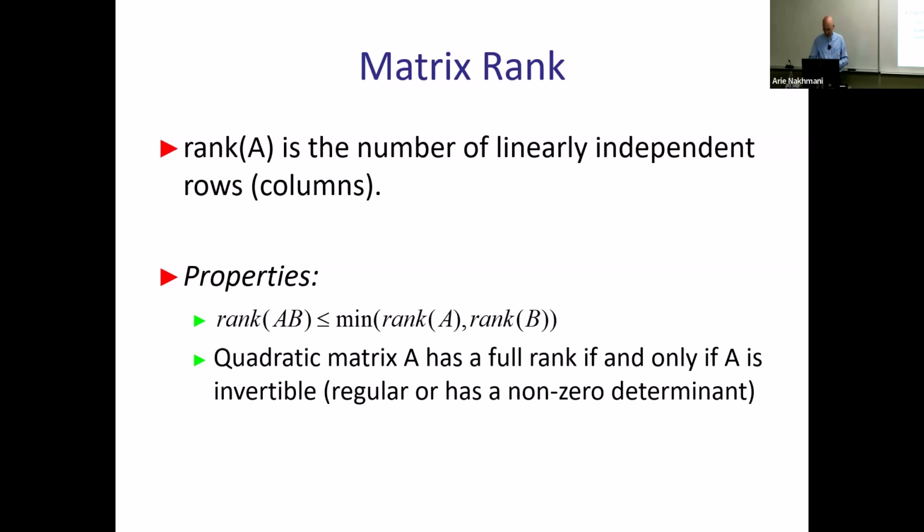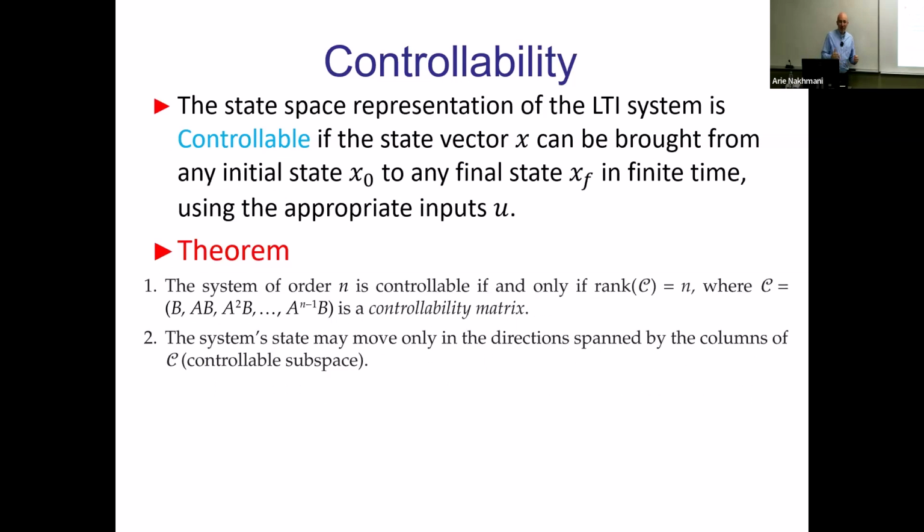All right, this is about rank, and why do we need rank in general? Because of that important theorem, and this is the controllability property of any control systems, which is fundamental for understanding what you can control and what you cannot control in particular systems, given your matrices A, B, C, D. Controllability means that you can take the system from any initial state to any other final state in a given finite time, or a given number of steps if it is a discrete time system.